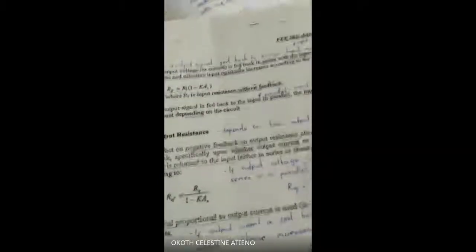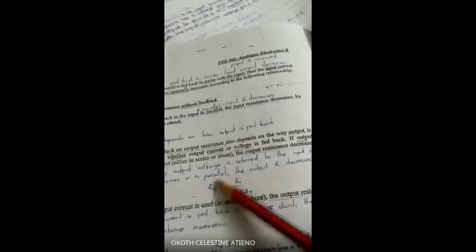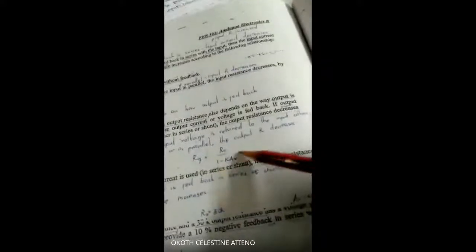And then for output resistance, we were saying that if output voltage is returned to the input, either in series or in parallel, the output resistance decreases. So if I return output voltage in series or in parallel, my output resistance with feedback will still reduce by this factor. We are going to do questions so that you understand what's going on. Yeah, so I think we can start doing questions on feedback.